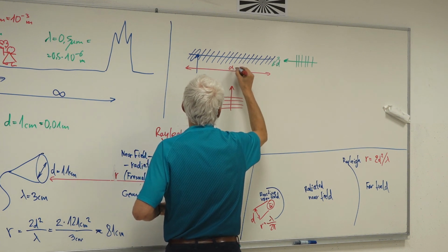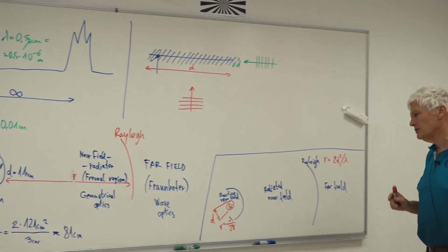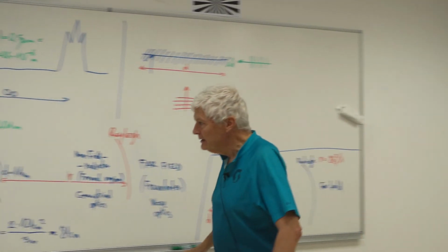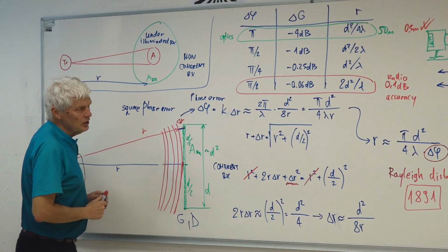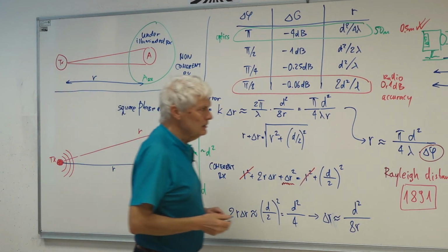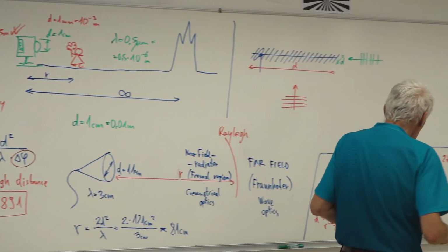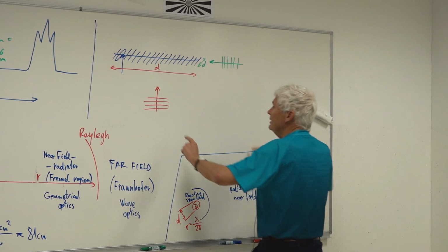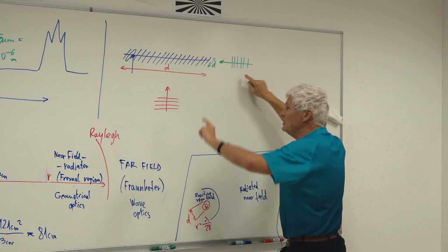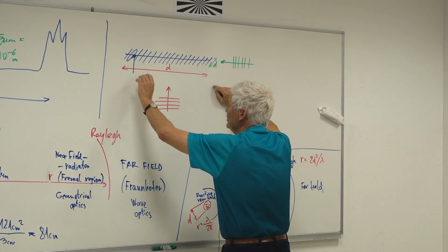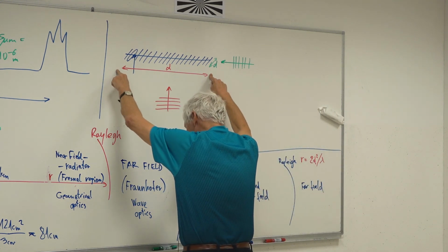Then D is here. So D should be always at right angle to the arrival of the waves to the antenna. So to know which dimension, this dimension should be always at square angle to the direction of the arrival of the radiation or departure of the radiation from the antenna. Now, this picture here, D may be a function of the direction. Especially for very, very long antennas. Some antennas may be very long. Depending what I'm measuring, it is not always practical to have this distance.